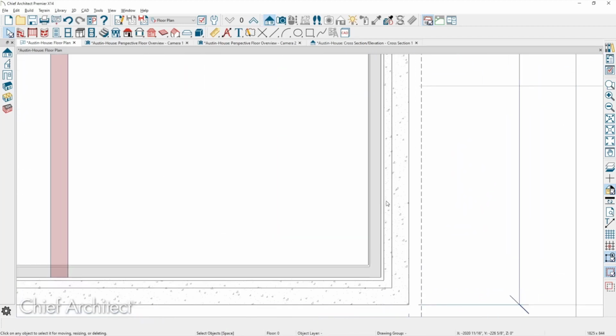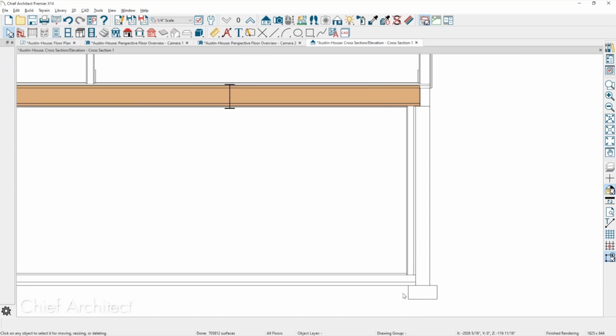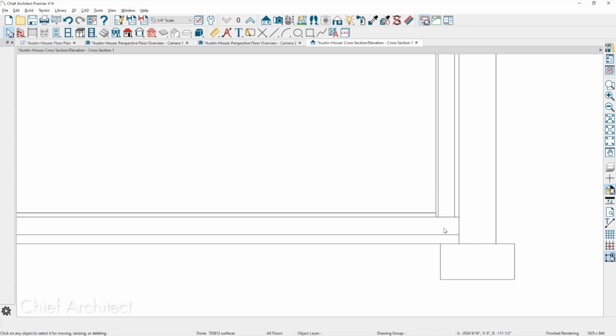As we zoom in a little bit closer, this is exactly as you might build it for a foundation and a basement that's enclosed with those furred framed walls. And you're going to get a better structure connection, because sometimes if you build it as one single wall, my footing extends down, and I probably could make a bigger footing to support that, but that wall may extend down into the footing. If it's a singular wall, the platform probably wouldn't build quite the way I'd want it. So I usually use a separate wall, a little bit more work, but it is structurally more accurate when you cut your sections. Agreed. Thank you.